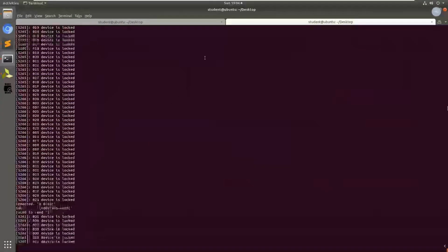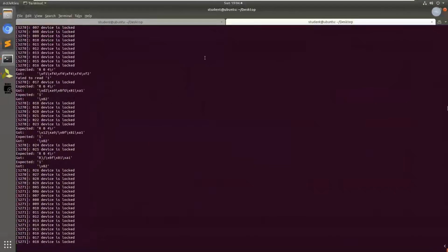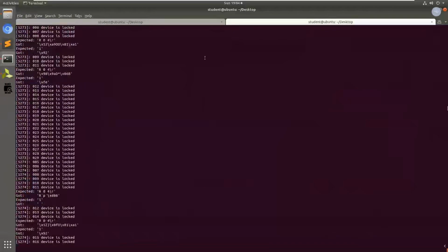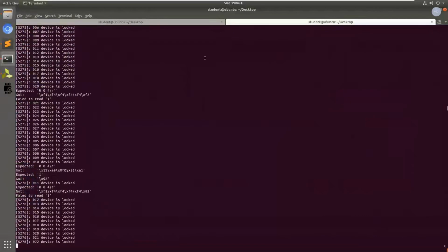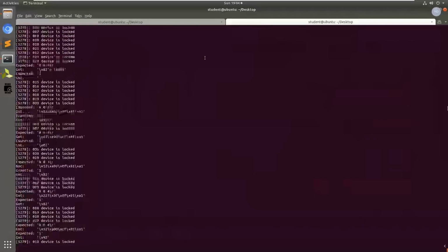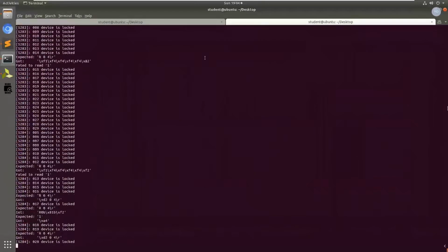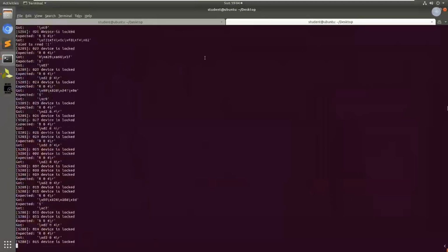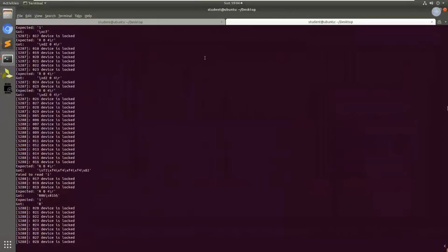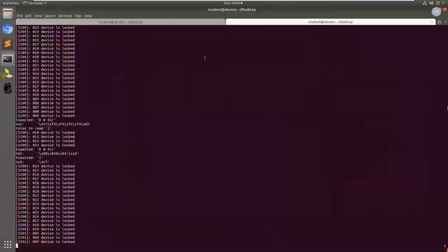One thing that you can actually do, so I'm not going to touch it so much, is lower the voltage and just see where the limit of the system is. So I'm going to start lowering the voltage a little bit, and you'll see that at some point we'll just get complete garbage. And so essentially right there, that means we've gone too low on the voltage. Otherwise, we'll just let it run.